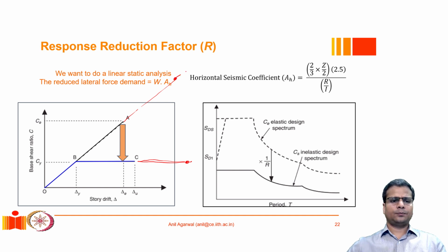In such a scenario, we can utilize a response reduction of up to this level. Whereas if the system is not very ductile, and at maximum we can utilize only this much yielding, or this much permanent deformation, my response reduction would be only this much. So this factor with respect to the elastic force that we would calculate here, this response R factor, would be very large in comparison to this R, and that is definitely a function of how much ductility is available in the system.